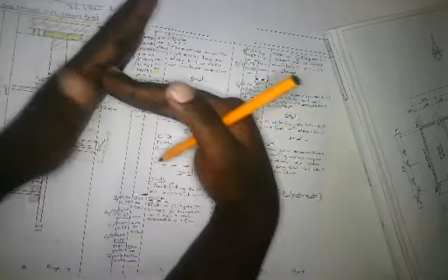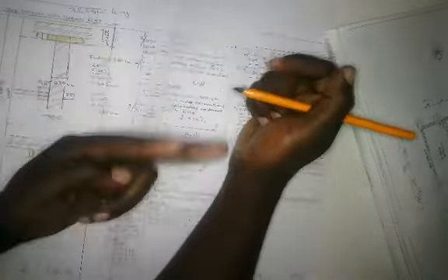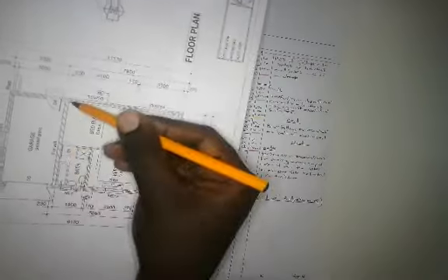I think, guys, that was what you were maybe having an issue with. Now what is important is that you go and identify in your drawing how many of the 230 walls are going against 270. So in this drawing we had 2, and here they are, this side and this side. So you have 230 versus 270 T's, okay.